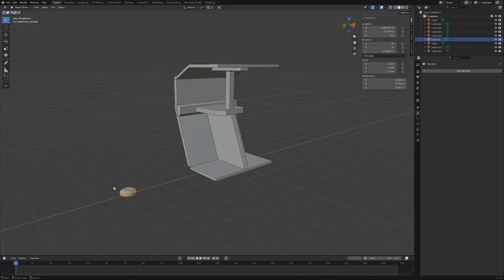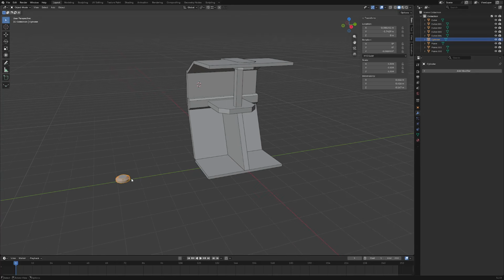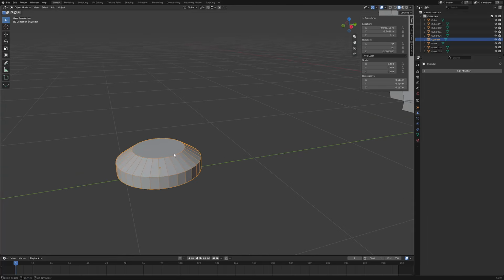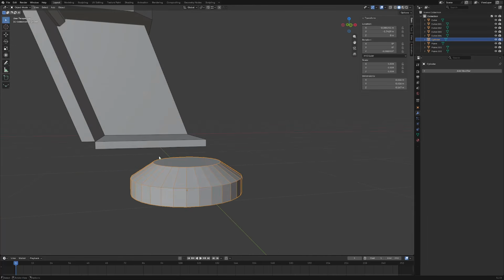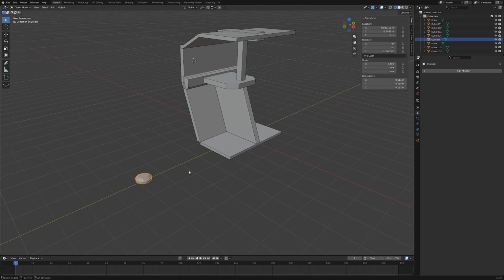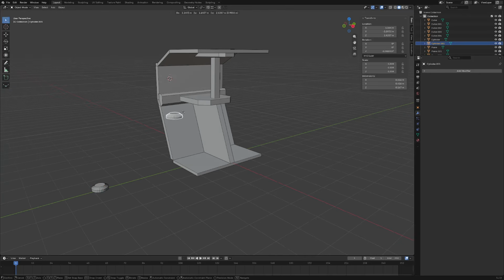But let's just say we got a detail. We're going to add it to this guy later on, perhaps, or maybe we add it right now. So if I want to add it right now, I don't necessarily need to group this unless it has other objects, right? So if I had other primitive objects here on this and I need to group it all together, then so be it. That's what I would do. You can add those primitives to it later on as well, so we'll be okay. Otherwise, you can Alt D and just use it as a link duplicate.